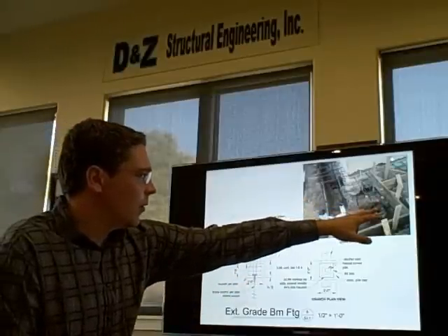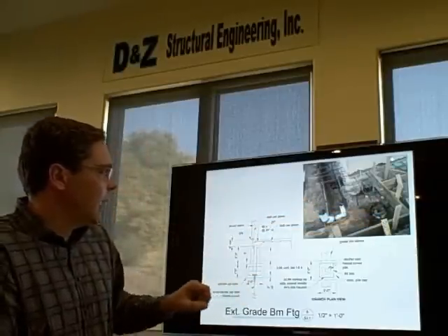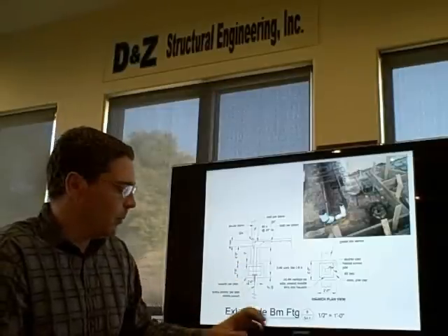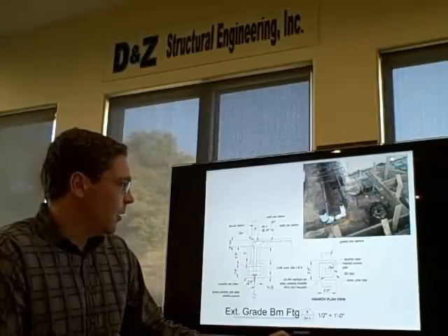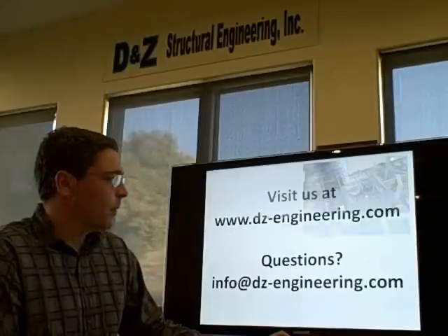This is the screw anchor head that's screwed into the ground. It's a dish plate, and then we pour concrete element on top and then support grade beams on top of those. These are all different pathways that we can go down with the support of a soils engineer to provide for a competent bearing on our